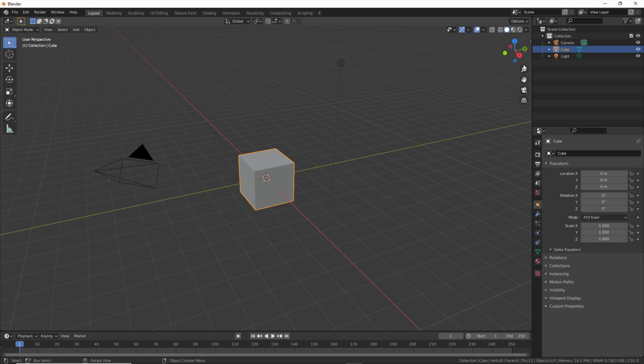In this session I look back at how I could split a plate in Blender, a plate as in a 3D model of a plate. And we're going to do that with the help of the bisect tool in edit mode.